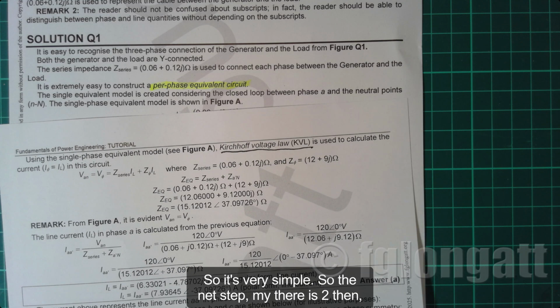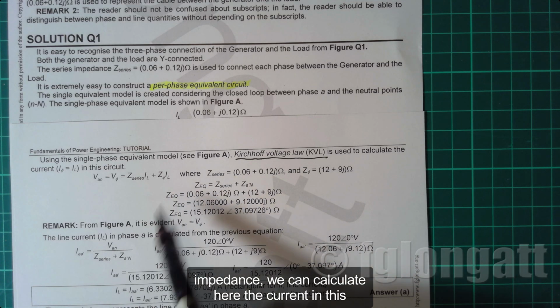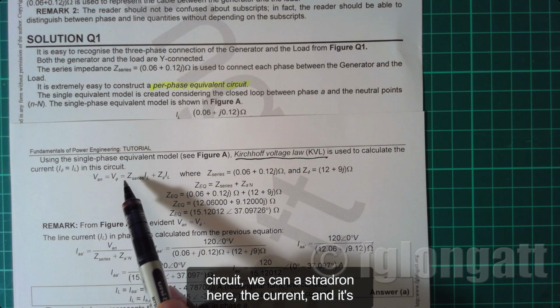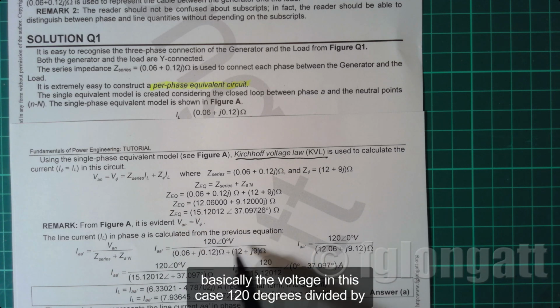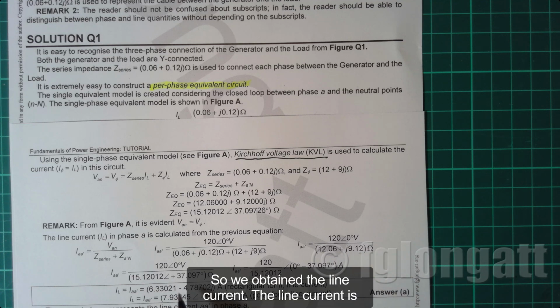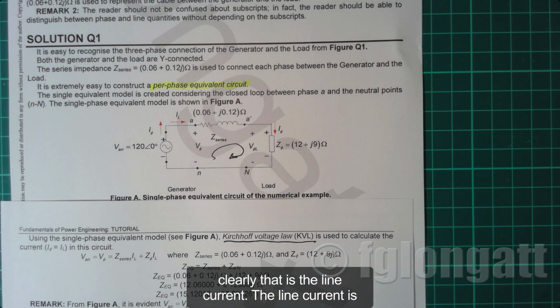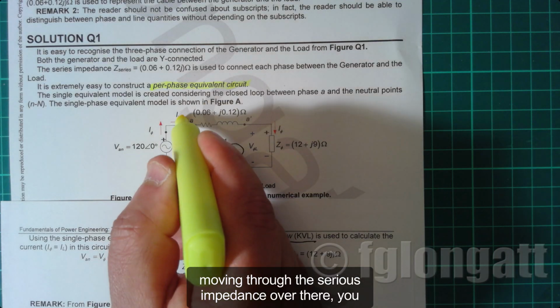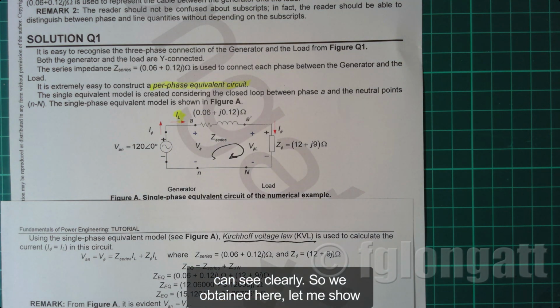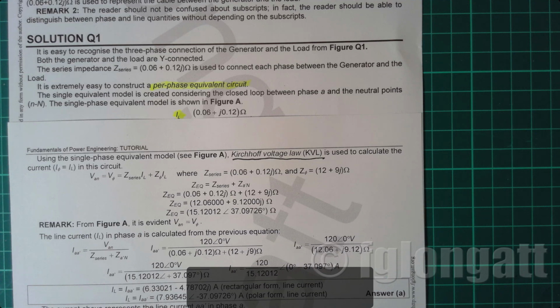So it's very simple. So the next step, my dear students, is, obviously, if we have an equivalent impedance, we can calculate here the current in this circuit. We can extract from here the current, and it's basically the voltage, in this case 120 at an angle of 0 degrees, divided by the equivalent impedance that we already calculated here. So we obtain the line current. The line current is the current that is moving over there. You can see clearly that that is the line current moving through the series impedance over there. Let me show you the numerical value. You can see that the numerical value is 7.93 at the angle minus 37.09 degrees. Okay?